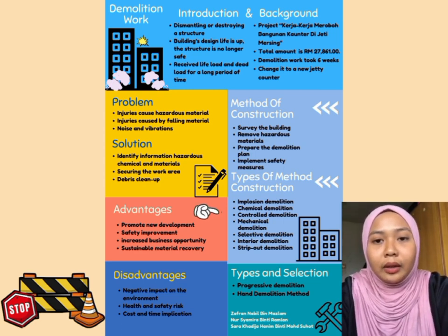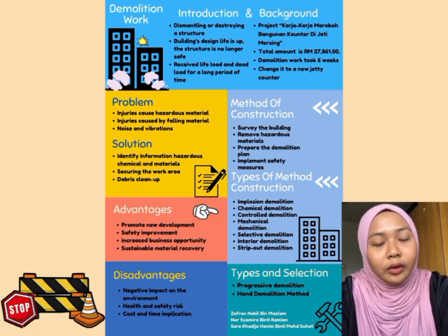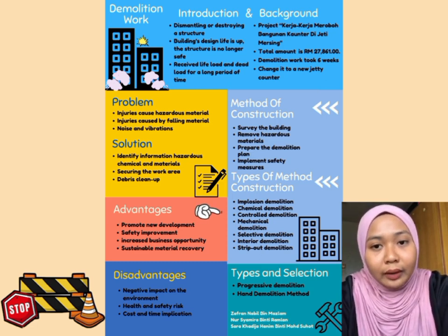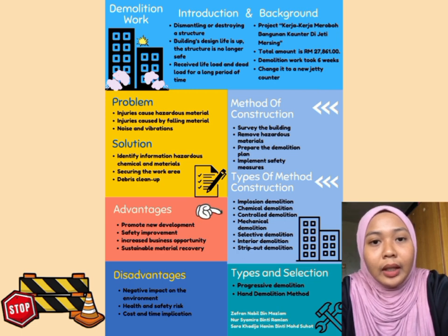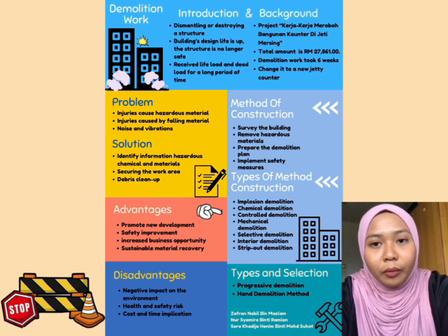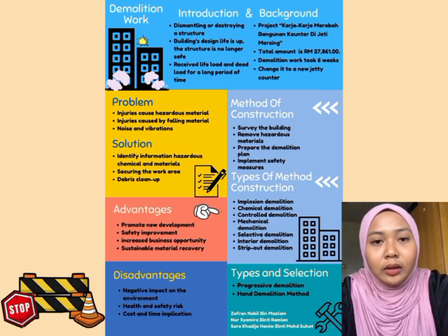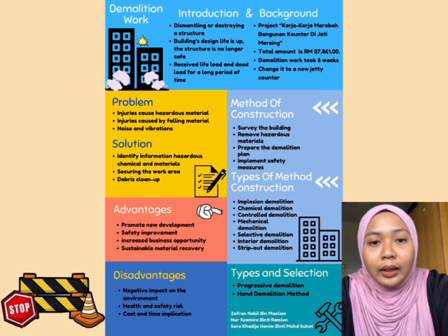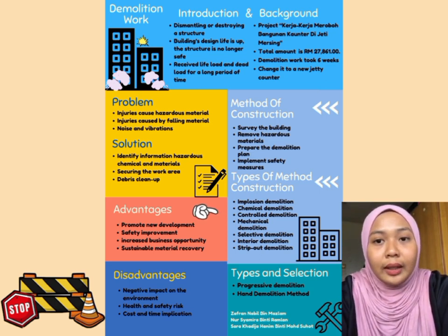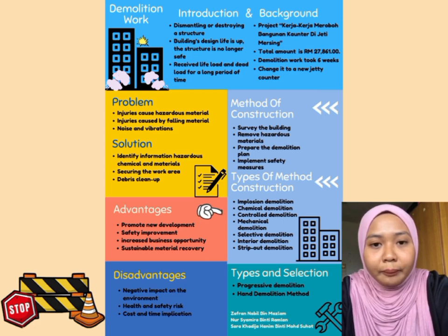Next, the chemical demolition method. The chemical demolition method, without the use of explosives, is safer and less expensive. In contrast to blasting, there is no lengthy permitting process. The rest of the structure is safe from vibration and important stone portions can be retained. Moving to the next method that can be used is the controlled demolition method. It is a demolition process that entails tearing down buildings and structures in a safe, supervised manner in order to obtain the greatest outcome in the shortest amount of time.